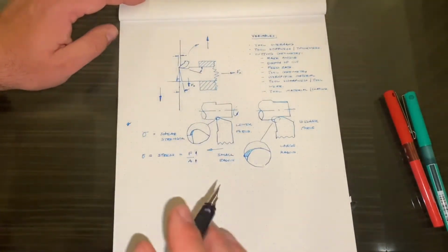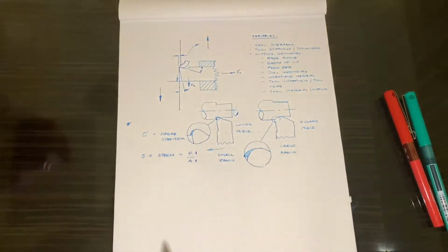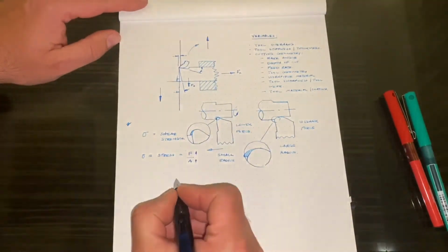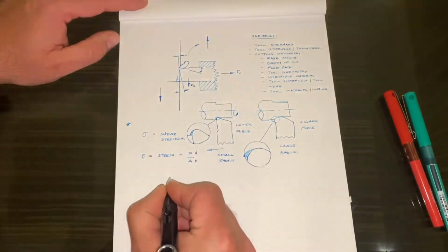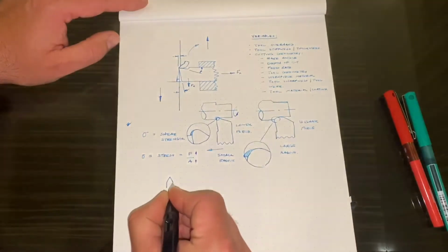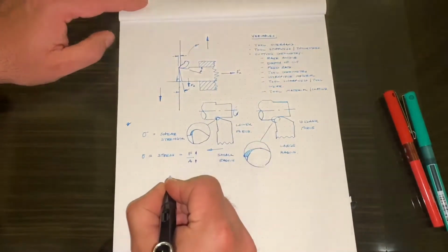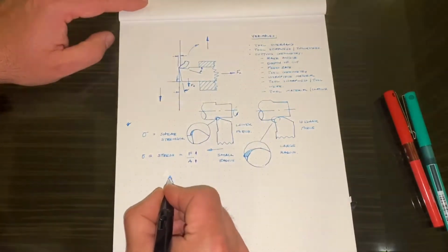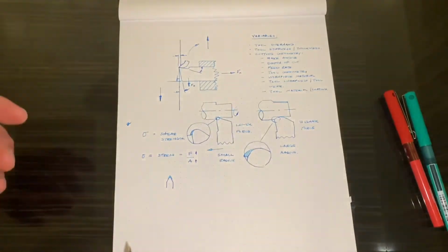This is why on one of my previous videos I was speaking about plunge turning a thread, where the threading tool looks something like this, and where the chip is formed all the way around the tool here, and the result of that is high turning force. It puts a lot of stress on the machine.